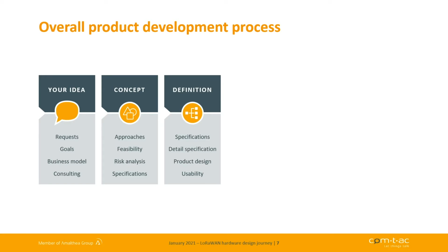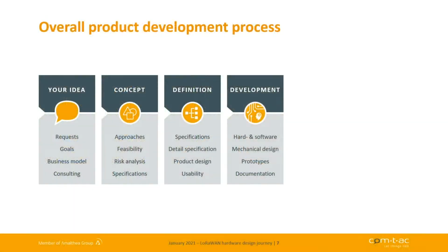We have really big experience even with norms and regulations, especially in the ISM frequency band. We have different regions worldwide, and you have to take that into account even when you design the payload, for example, in a LoRaWAN device. Then we really start with the development. We make the schematic and layout, we build a prototype, write firmware and test it, and we go to certification with the device.